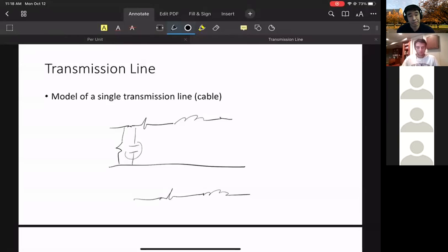So for most problems, if we have multiple transformers in a line, we'll make the secondary voltage the same as the primary voltage for the second one. So there's not an ambiguity of which base you choose. Do you go from this direction or from this direction? It could go from both directions, so for most problems we'll try to remove this ambiguity of which way you look at the problem. So you do that for transformer 1, and then adapt that to transformer 2.